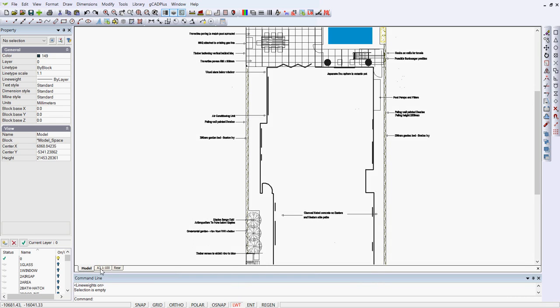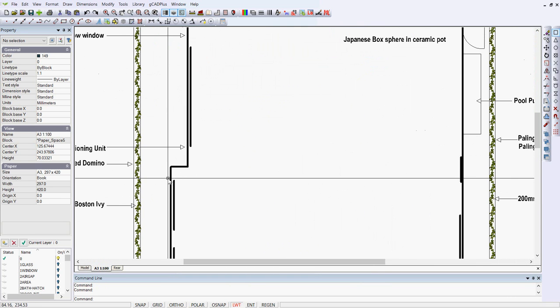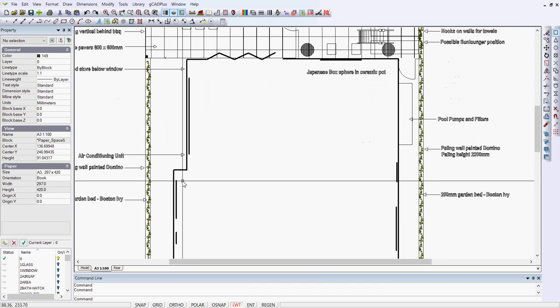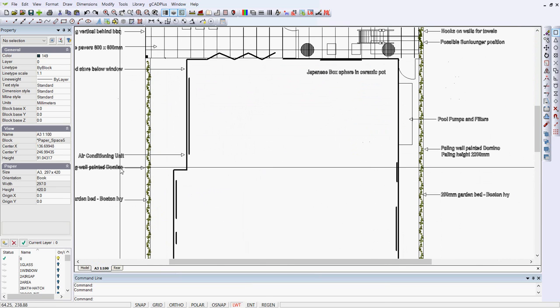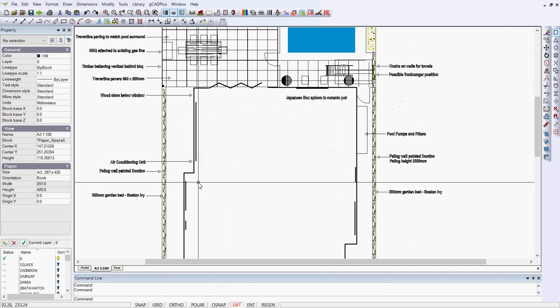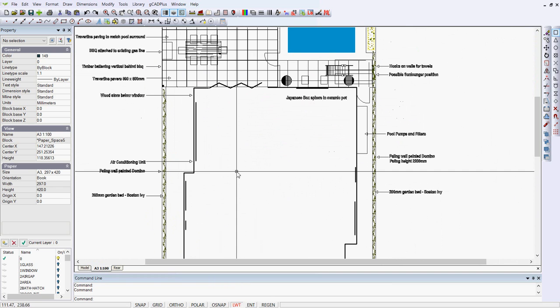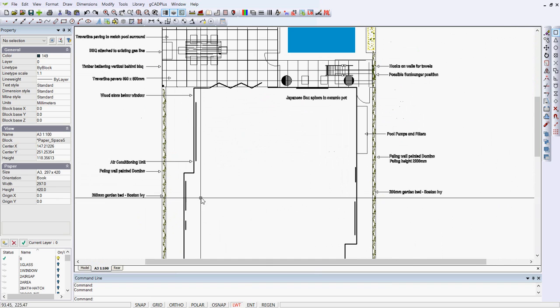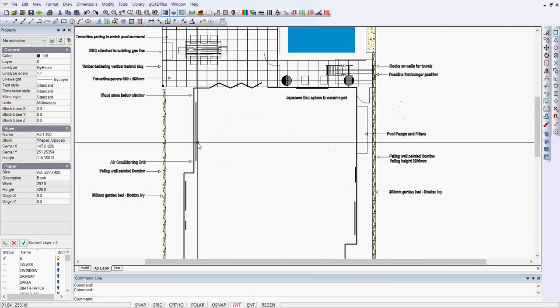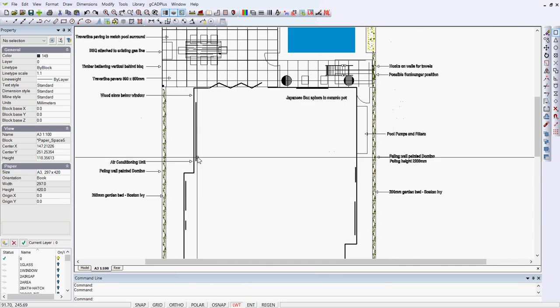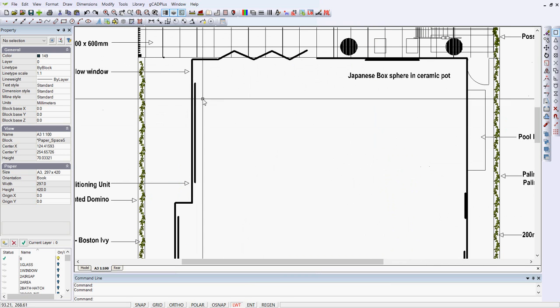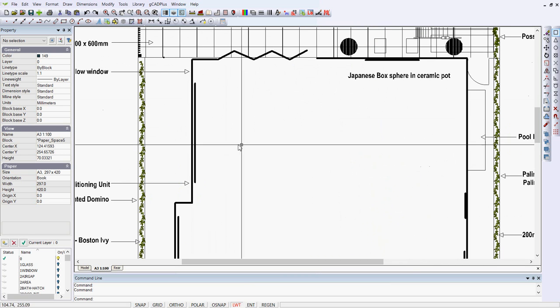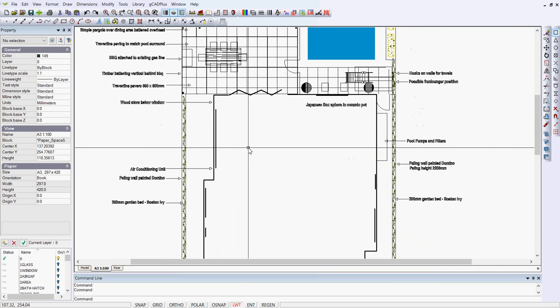And when we go to the A3 sheet and we zoom in, you can see there's the outline of the footprint of the house with all the other line work around it, including the text being quite light. So I'm quite happy with that. What I would draw your attention to, and I think it's very clever, is that the windows in the house are just placed by a vertical line or horizontal line just inside the exterior wall of the house footprint.